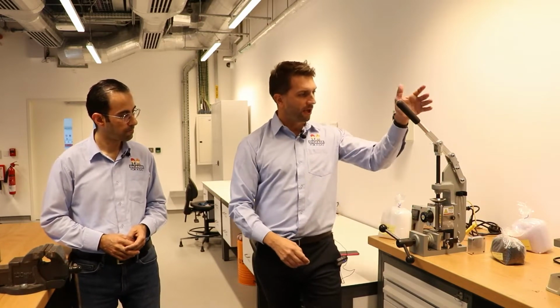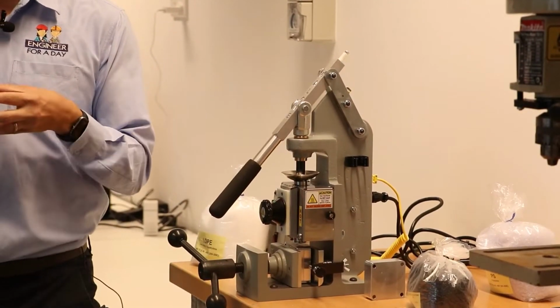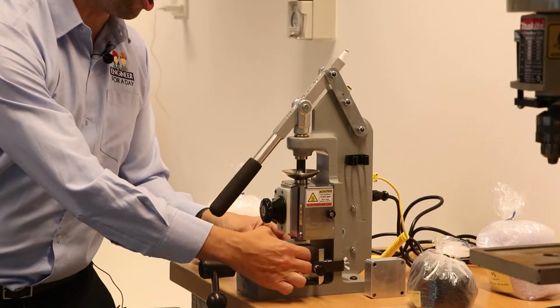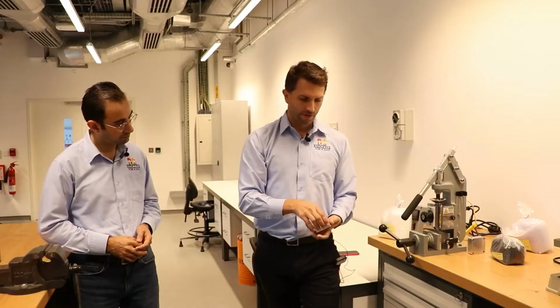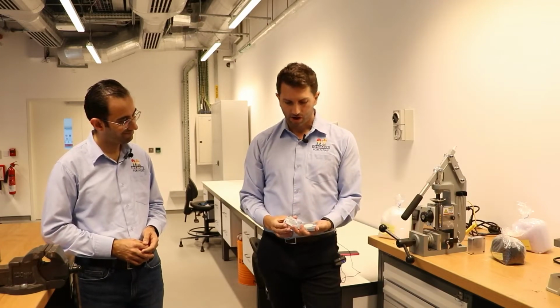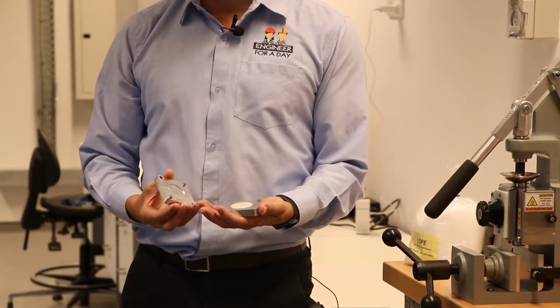So now we have our hot molten raw material and we have our mold. We clamp it up and we push this down, effectively extruding and injecting that hot molten plastic into the mold. And then when we open it up, we should have, well, one that I prepared earlier, our simple plastic product once it has cooled down.